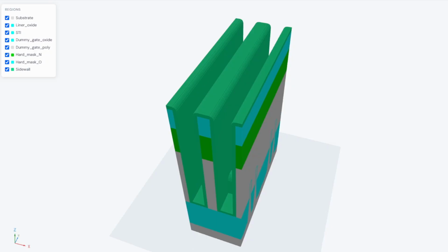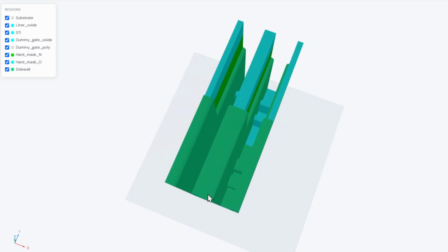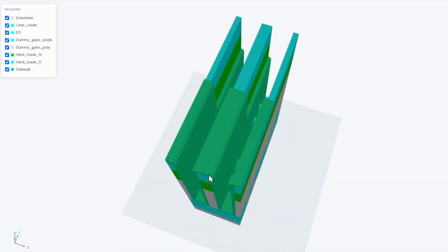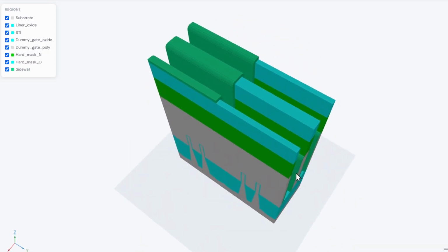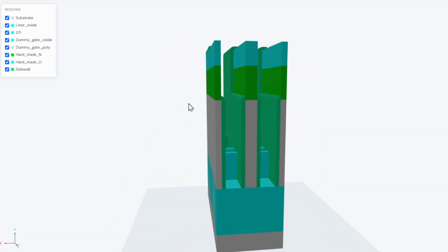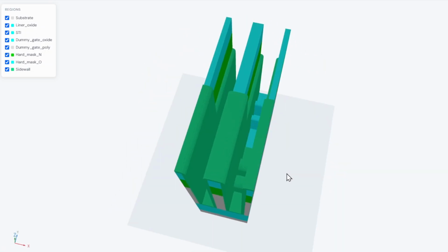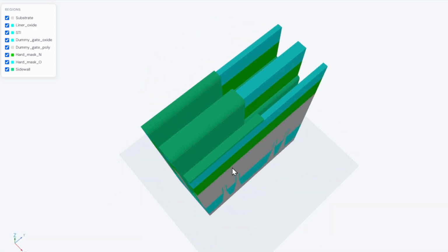The N MOSFET part is preserved and protected, and only the part corresponding to the P MOSFET will be etched away. Now you can see that this N MOSFET is saved from etching, and we still have a P MOSFET where sidewalls are eliminated, and this is the remaining sidewall.